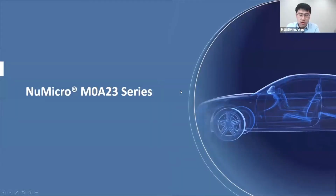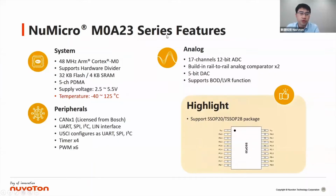Okay, and I have introduced our NUC131U. It is for automotive, and the next one is our M0A23. It is for both automotive and industrial applications. This slide shows our M0A23 series features. This microcontroller is a little bit different from our NUC131U. The first is that the temperature is up to 125 degrees. And the flash size is a little bit smaller than the NUC131U. It provides up to 32 kilobytes of flash.